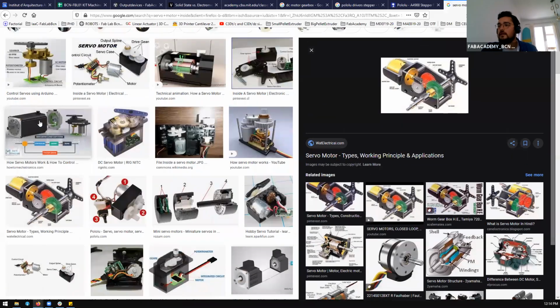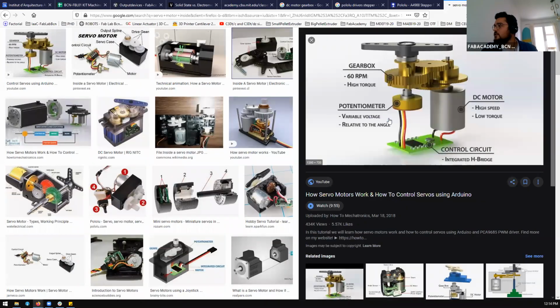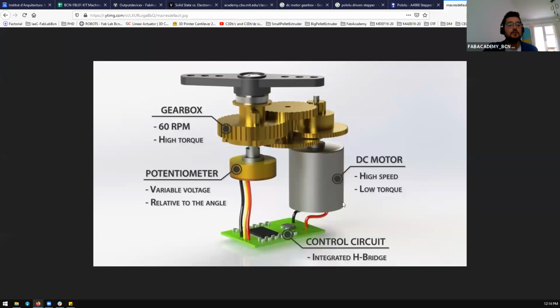Go back. So with a DC motor, we cannot control the position. What we do is have a lot of reduction, and we work with a DC motor with reduction, and the last gear is connected to what? A potentiometer. With a potentiometer, you can measure analog signals, no? From 0 to 1023. So when we rotate this guy, this moves the potentiometer to a certain position.